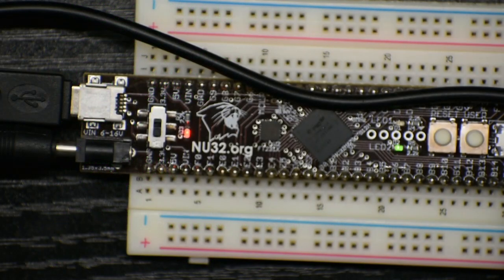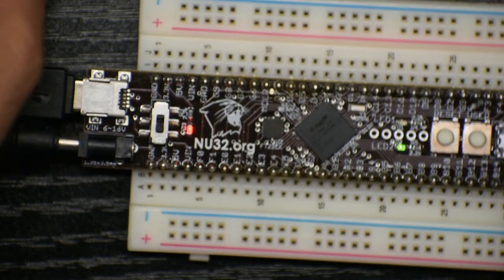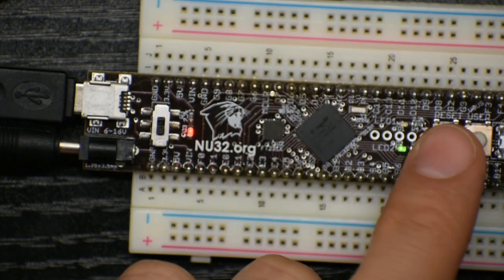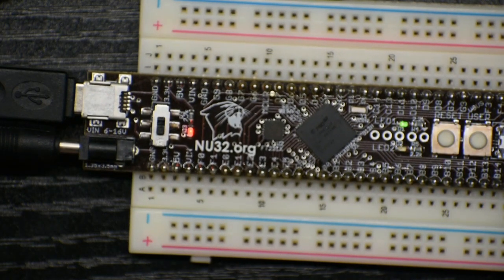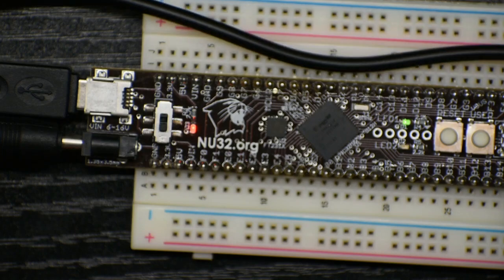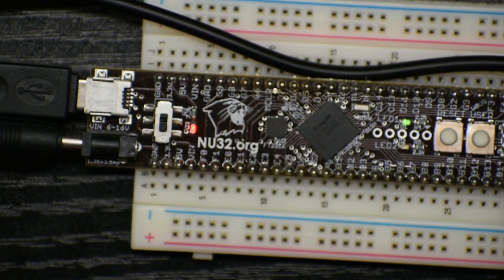So we're going to practice this a bunch, and you'll get used to putting your PIC into bootloader mode, using make to compile your code, and make write to send the code, and make PuTTY or make screen to communicate with your board.